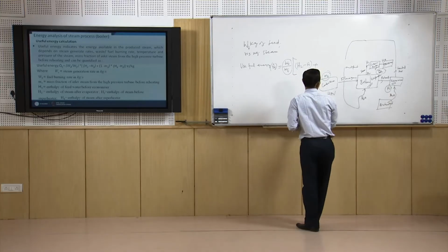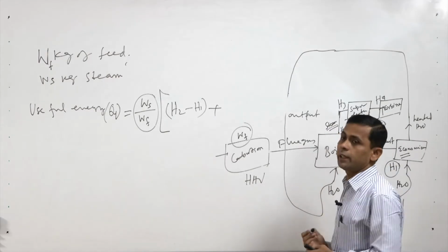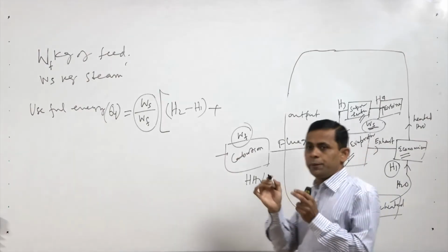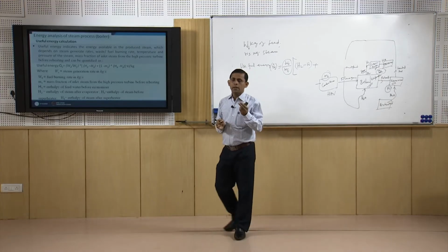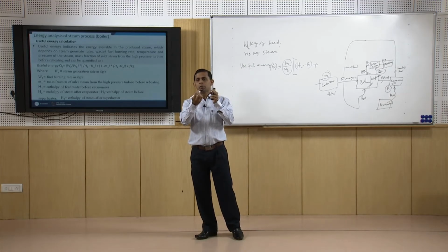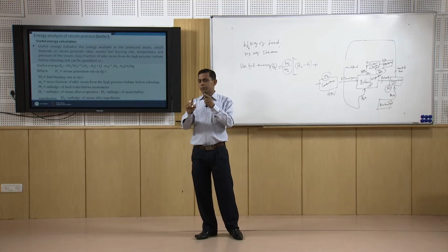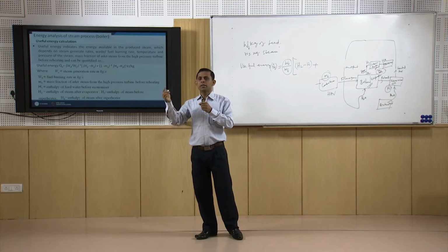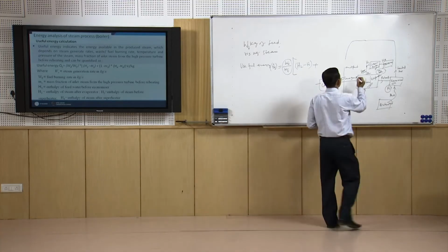Plus, here one interesting point is that we are producing saturated steam. If in our plant you have a number of turbines, the one turbine will be at higher pressure. So, higher pressure steam will exit from the turbine after use and it will have lower pressure. It may be possible that if the downstream turbine is using lower pressure, the exit from the first turbine can be used here.